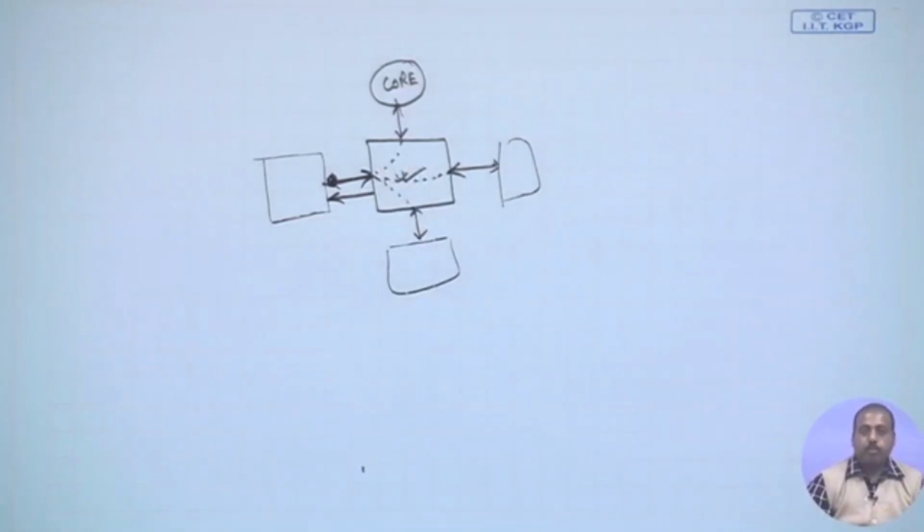So, there has to be a decision module which looks into the destination address of the packet that has arrived, and accordingly decides to which port this incoming packet should be put. We have a number of input ports. Every channel, or every primary input that we have, goes into one input port, which we call IP.